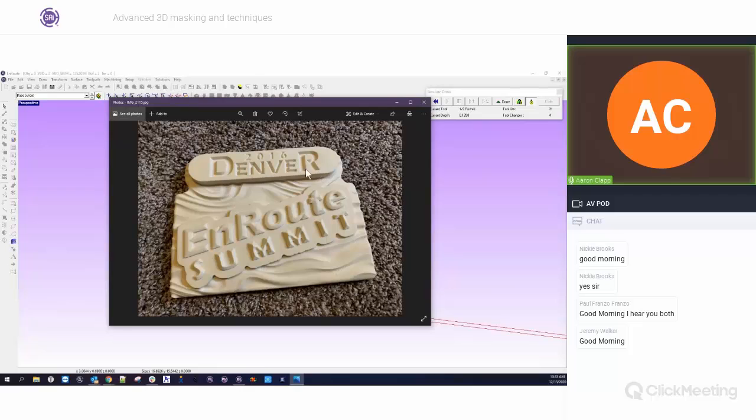Up here, we didn't have to worry about that because the letters sink down into the material. Up here, you'd have to create another mask for the letters so that when you mill out this flat piece, it only mills out these areas and leaves these nice little standing pieces, where you can come back later and apply a different toolpath to just the standing letters. So this is another good example of creating a part in EnRoute that mixes 3D with 2D toolpathing using masking and layers. Hopefully this gives you some ideas to think about.